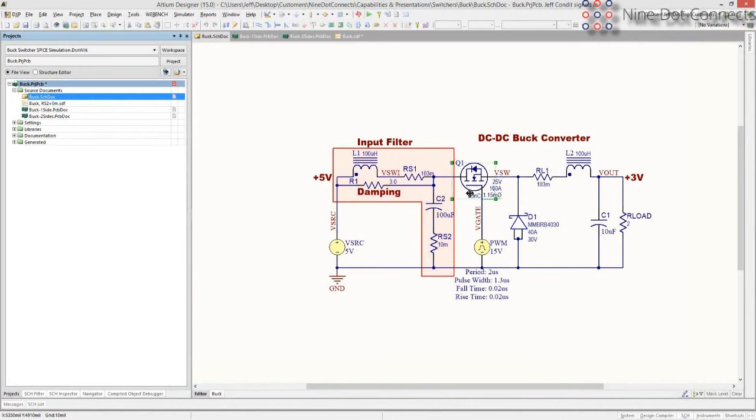Well, part of the time the current flows through the MOSFET, part of the time through the diode, and when the MOSFET is on, it's actually drawing it up through the capacitor. So that's really the place where the currents are switching. Let's look at that path.